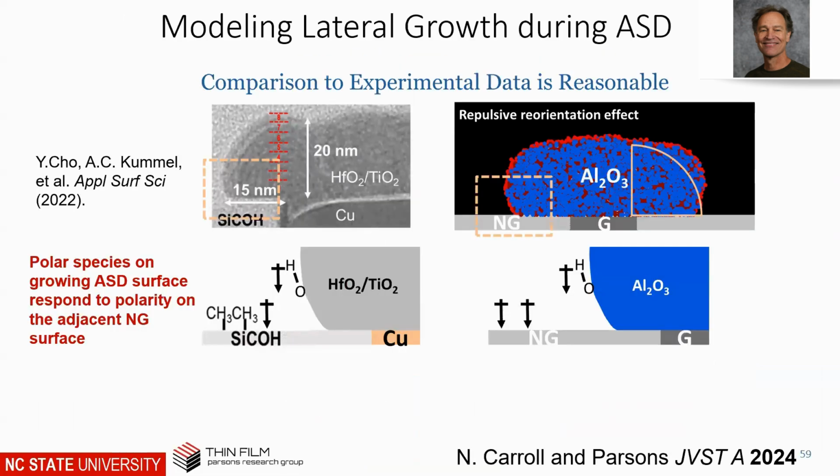Thanks, Greg. What do you think is the driving force to your defects, your 93% selectivity? What do you think is getting down into those trenches? Water is a perfect reactant for ALD. And it is the perfect problem for area selective deposition. So the best ALD processes use water. And so the perfect ALD process is a lousy ASD process. So we need new ALD processes that don't use water.